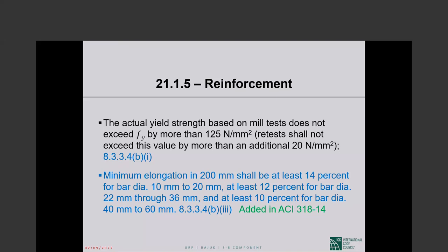That beam, stronger in flexure, will attract more shear force to itself in an earthquake. And we will not be correspondingly increasing the shear strength of the member, thereby making brittle shear failure more likely. This is why we absolutely do not want the yield strength of the reinforcement to be much higher than the specified value. This was a serious problem with structural steel.